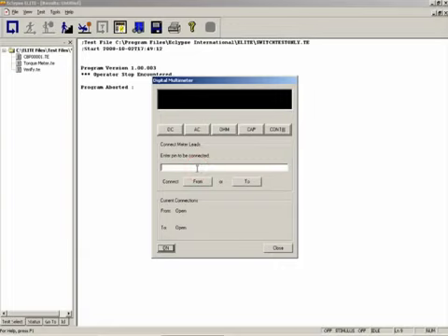Select the address that you wish to use or refdes and from. Then type in the refdes that you are going to and select to. Ensure that you select the On button to turn on your virtual DMM. The DMM is part of your analyzer measurement bus. Select DC for DC measurement, select AC for AC measurement, select Ohm for resistance measurements, and capacitance for capacitance measurements.